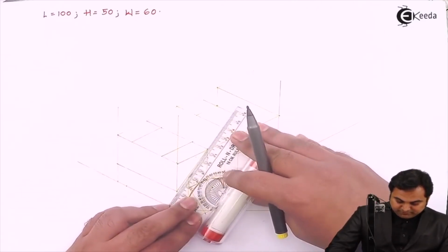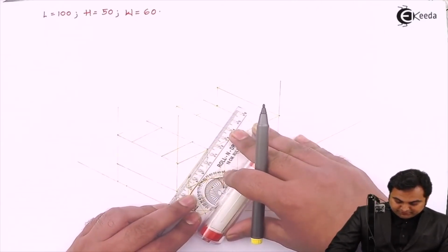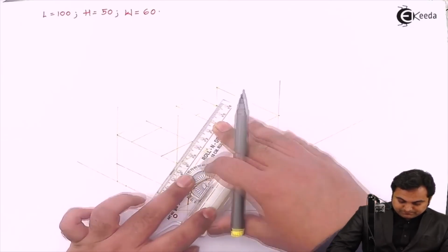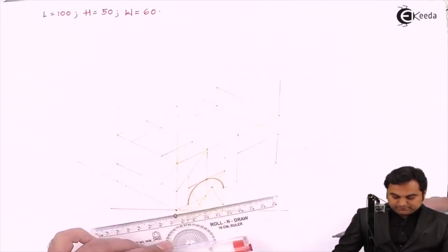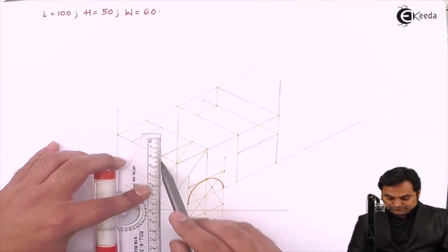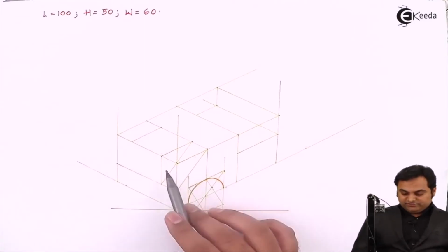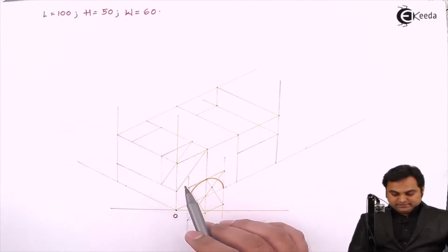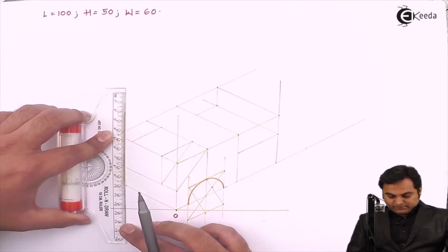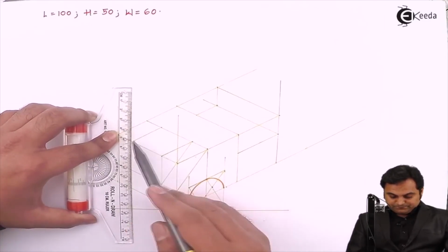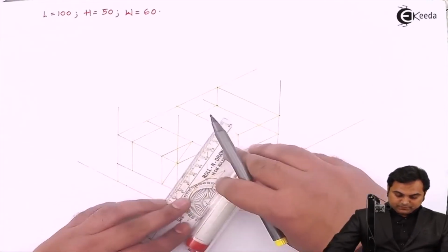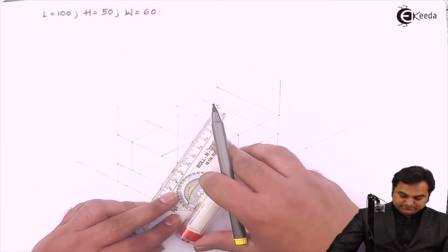here this 15 mm width I have already taken. From that, I am going to draw a parallel line, a light parallel line. Next, joining these 2 points is going to give me the surface as I can see here. And similarly, here also I am projecting a light vertical line. Then the surface is parallel, so I would be connecting them.